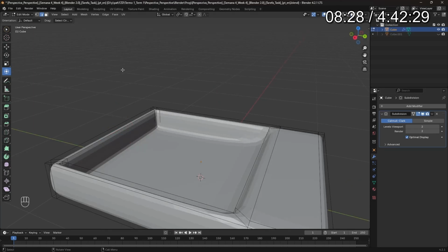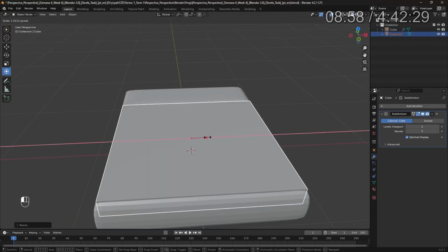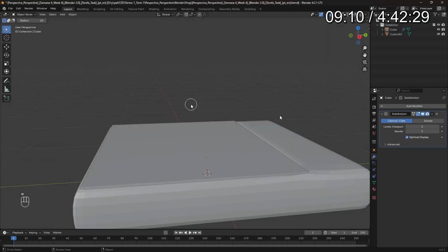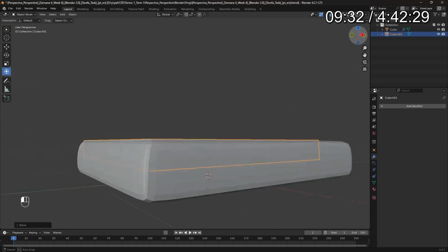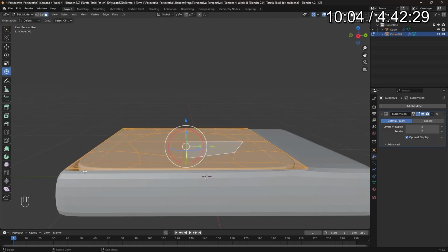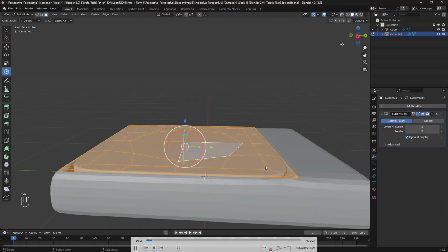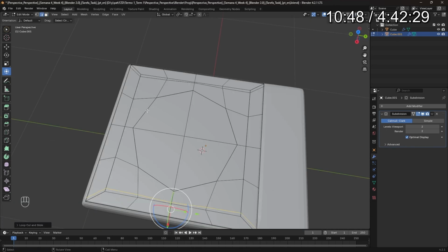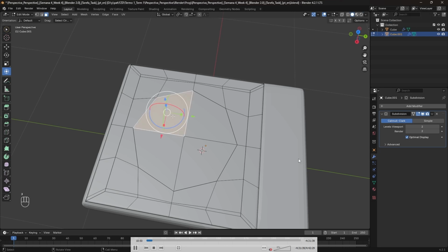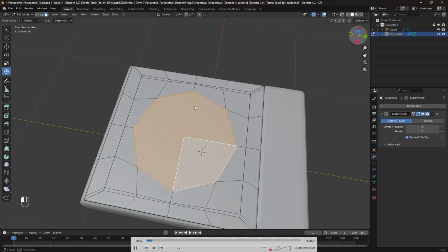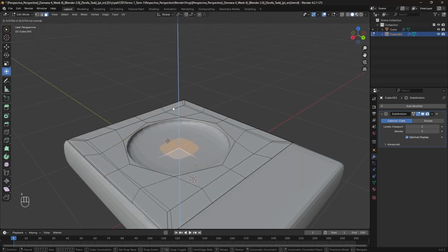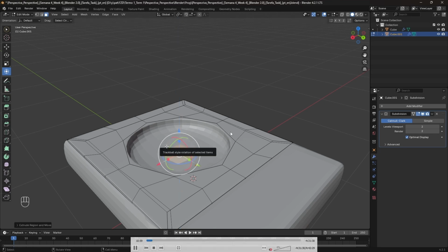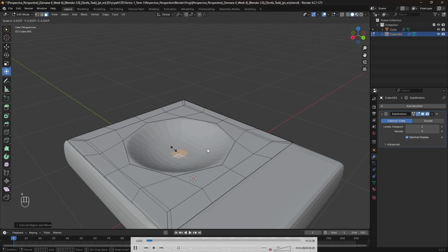And then I went back to this piece, and I also applied the subdivision surface modifier. So you can see over here that I applied it, and the idea was also to create new cuts. After that, I was able to do the thing that I wanted. So the idea was to extrude this downwards and make the adjustment. So you can see that now I have that kind of region to place the stove burner.